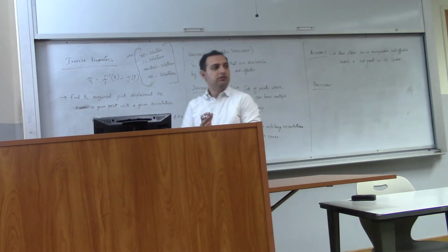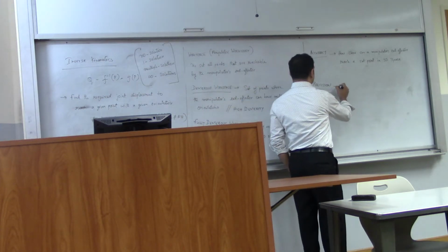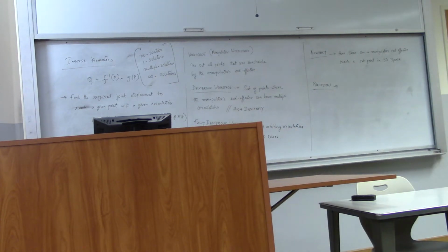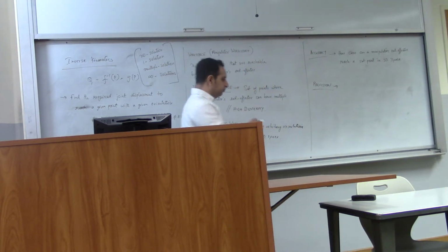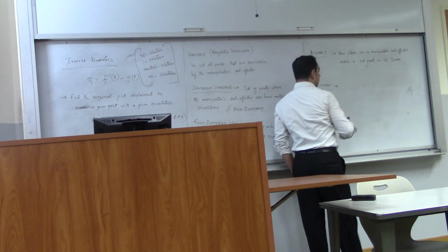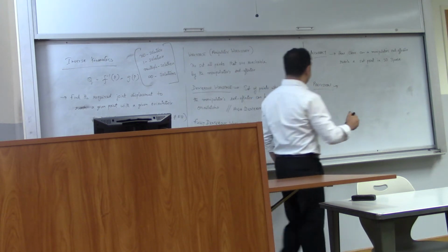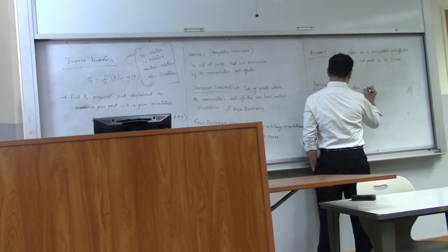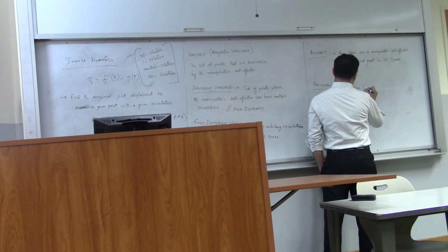So how do we define precision? What is precision? Minimum possible movement. No, the thing is, most manipulators do a task repeatedly over and over. They're doing the same pick and place jobs. So this is how close a manipulator can go to a previously taught point. If it's doing that again and again, is there an error creeping up or does it maintain a specific accuracy? If the accuracy keeps on changing, then it is actually highly imprecise. But if it maintains a particular accuracy, then it's fine.